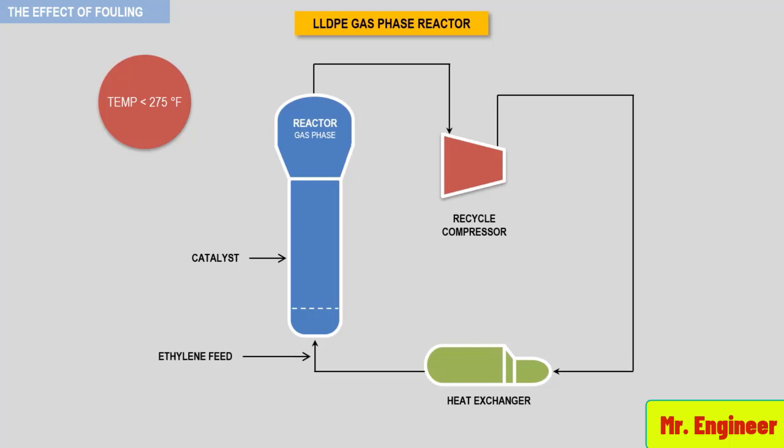In these services, the temperature of the process gas within the compressor must be kept below the critical temperature that will initiate the formation of polymers. This temperature varies with the process and should be in general below 235 degrees Fahrenheit to avoid problems.